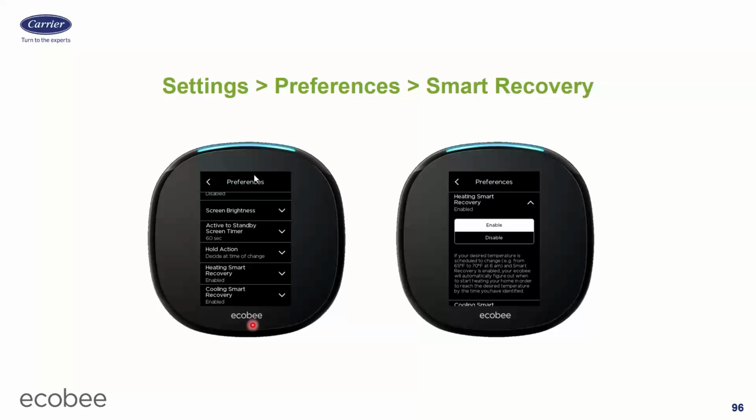Or they might look at their trend graph, which I'll show you later, and they may see everything looks normal on the trend, but then for some reason at like 2 a.m. it ran the heat for like half an hour, randomly for no reason. You're like, why the hell did it do that? All right. It was learning. And once it learns, it's going to be a little bit better, and then it's going to save you more energy if you're patient and wait for it. So a lot of people will tell you to turn it off. I'm going to tell you to leave it on. Most people have it on because they don't know it exists, and it works fine.